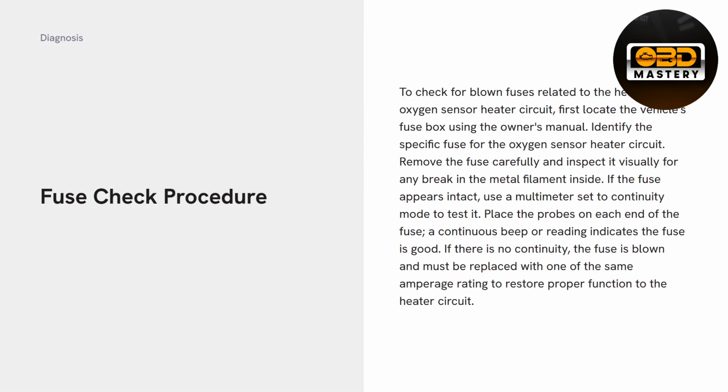Now, the fuse check procedure. I would read it all, however, it's pretty easy. Locate the fuse box in your car. You can usually find it in your owner's manual. Once you know where it is, look for the specific fuse that controls the oxygen sensor heater circuit.